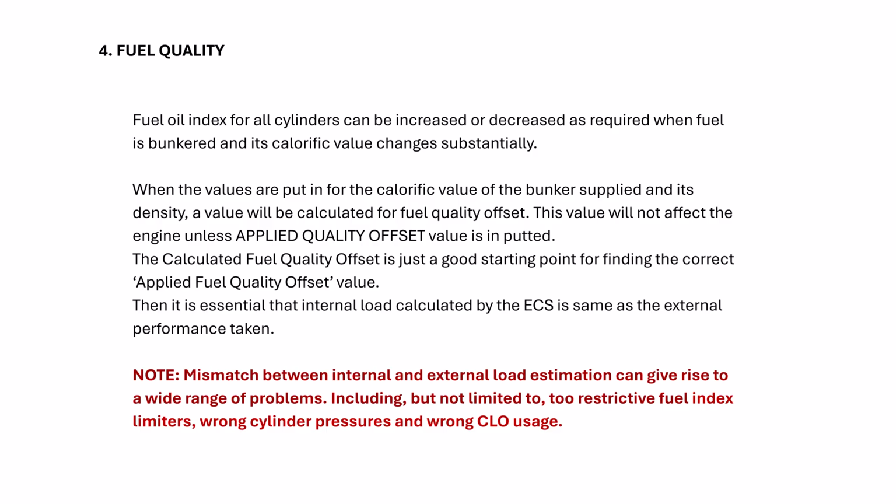When the calorific value of the bunker supplied and its density are put in, a value will be calculated for the fuel quality offset. So when you receive the bunker, the calorific value and density are given by the supplier. You put these values in your system, and a fuel quality offset will be calculated for you. But this calculated value will not affect the engine unless you apply it. There are two things: the system calculates the fuel quality offset when you put in the calorific value and density of the new fuel, and then this offset has to be applied. Otherwise, the engine's calculated power will be incorrect, because it will continue to calculate based on the older calorific value.